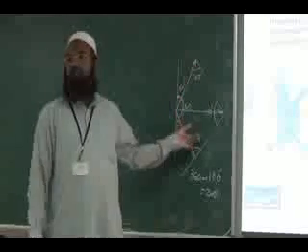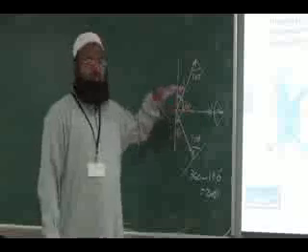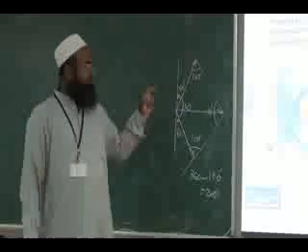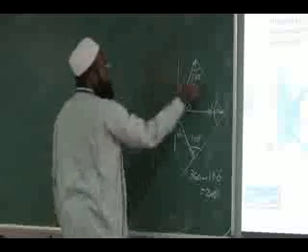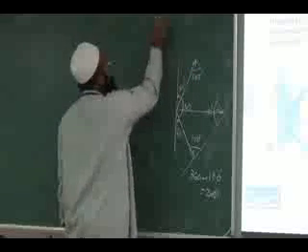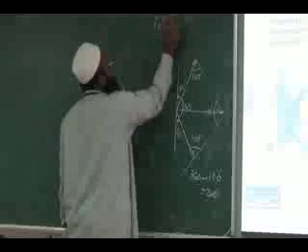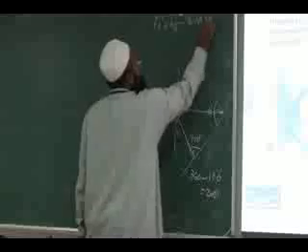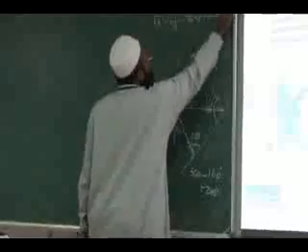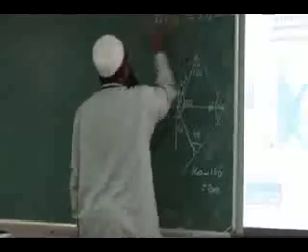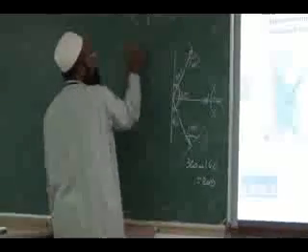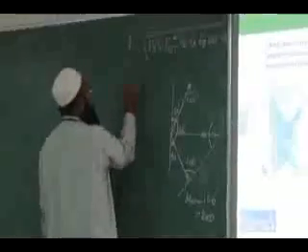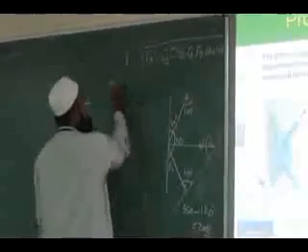Okay, so now you have the angles of the parallelogram. Either you consider the cosine rule or the sine rule, you can solve it. Considering the cosine rule, you will have F1 square plus F2 square minus 2 F1 F2 cos 100, which will be your resultant. You can find out the magnitude, then the angle can be found by using the sine rule.